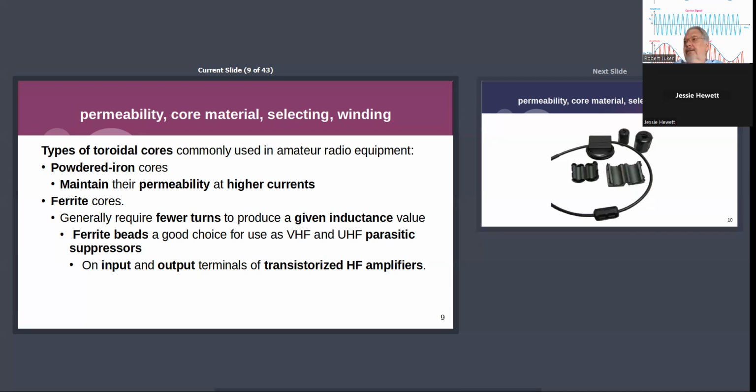Ferrite beads is another example. It's kind of a toroid, and you can get them as what they call clip-ons or snap-ons, where it's split so that you can put it around an existing cable that has a big connector on it that you can't always slide a bead on. But you can also buy them as solid beads. They make very good chokes if you build it and put them on, about 5 or 6 of them on a piece of coax.